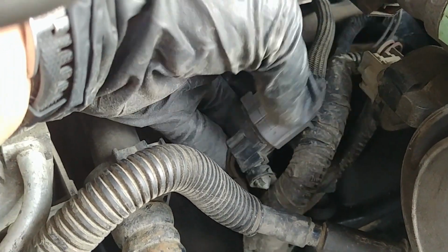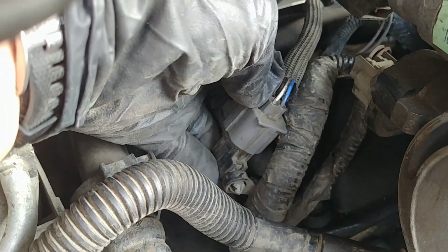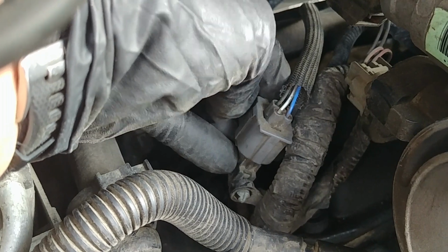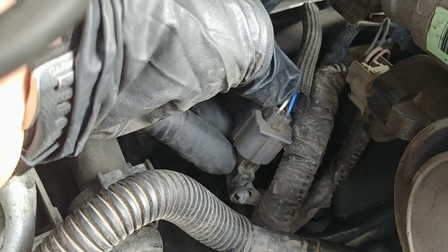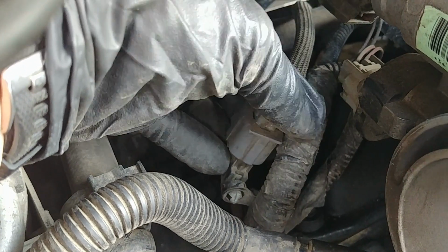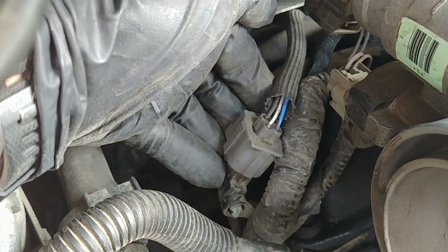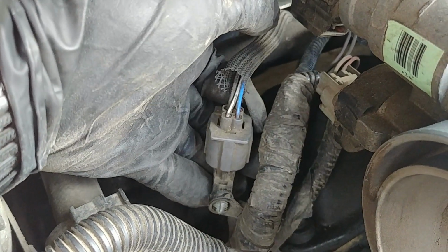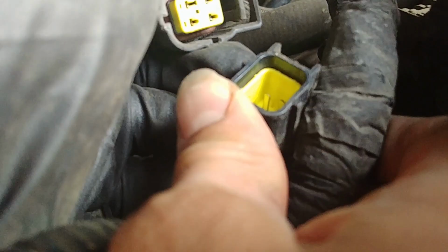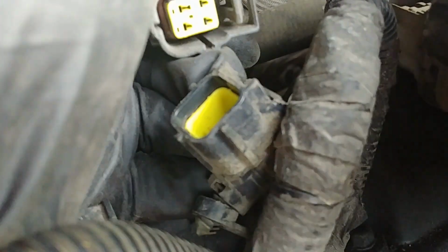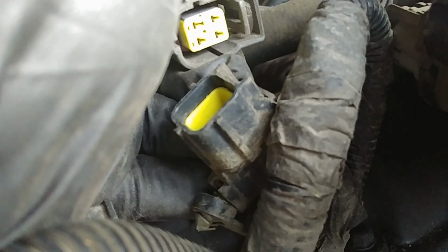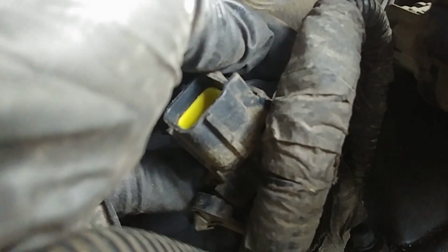Now we have way better access to the O2 sensor connector. This type of sensor has 4 wires. One is responsible for sensor ground, another is the signal wire, and the 2 remaining wires are heater wires, which is supposed to be the most reliable design. Alright, undo the sensor connector. It's pretty clean. We don't see any moisture or dirt here, which is a good sign. And we're going through all the causes and checking the power.